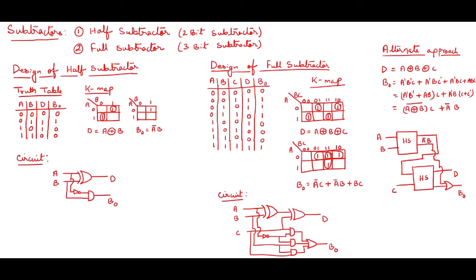Now this first line is coming in this way and getting over here, that is A XOR B is coming, so C is getting XORed, so D is nothing but A XOR B XOR C. But what will carry? A XOR B complement will come, because this part will again get a NOT gate over here, right. So I'll be getting A XOR B complement into C, right. So at this point I'll be getting A XOR B whole complement into C, and from above I'm getting A bar B. So this is nothing but the equation for borrow.